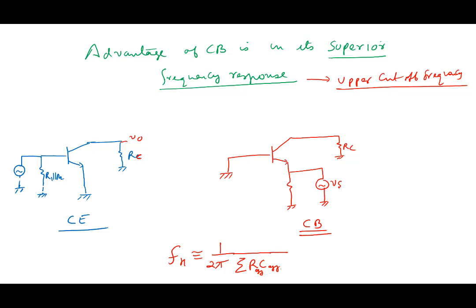Okay. Now, one of the issues with this common emitter amplifier is the following. Between here and here, we said there is a capacitor called C mu between base and collector, right? And if you recall, when we apply Miller's theorem, what happens to C mu? When I apply Miller's theorem to it, the C mu, which is there between base and collector, appears as if you take C mu out, and it appears as a capacitor here.